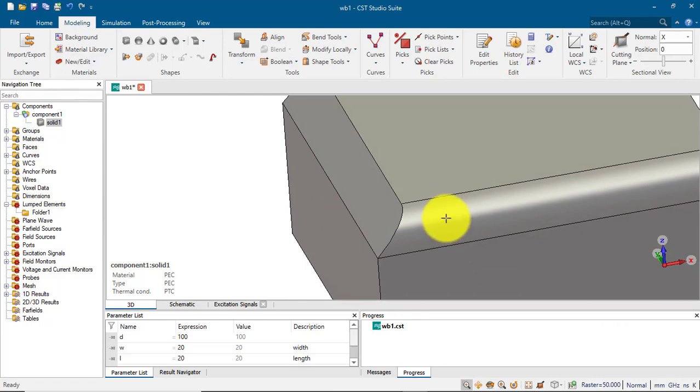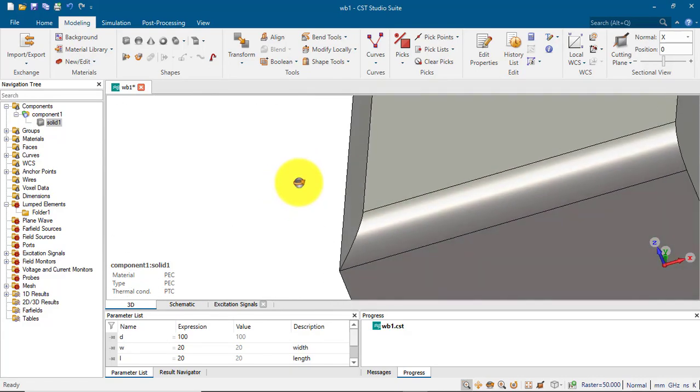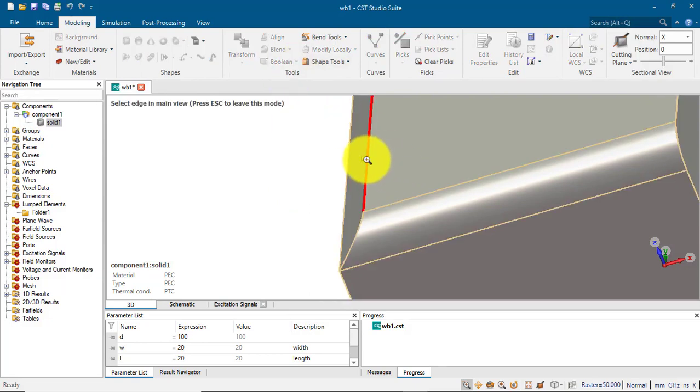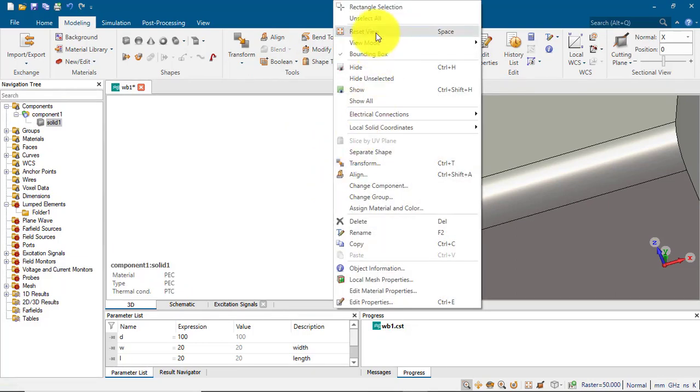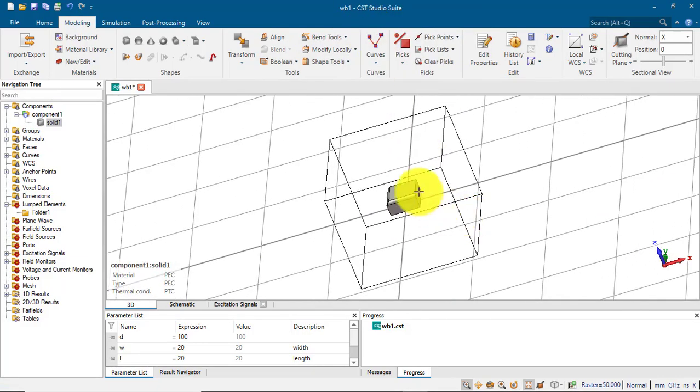As a blend, it will be a curve, but here it's a chamfer, so I cut it from it. Okay. So as I press E, you can see it also from here. If you look at it, this is the blend. It's a curve, while the chamfer will be a rectangle shape. I will cut it as a rectangle. Okay, this is chamfer edge. Let me clear the pick. You see, this is the way. Anyway, let me delete it or keep it.